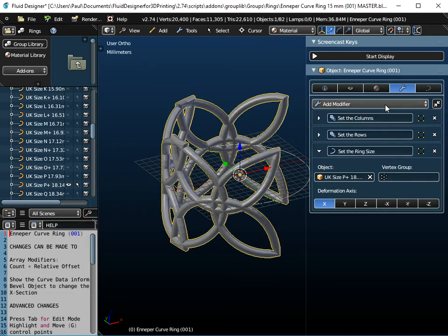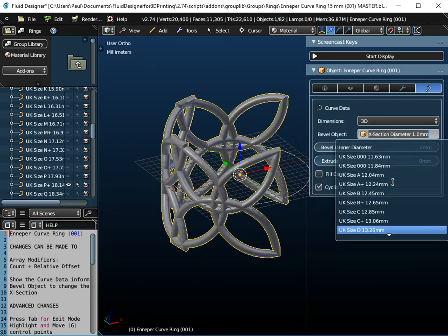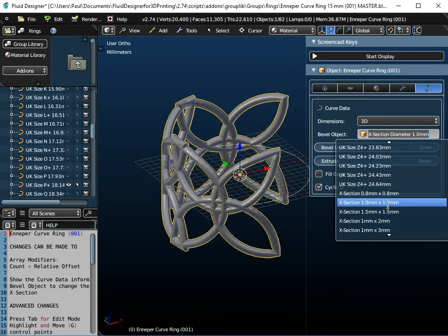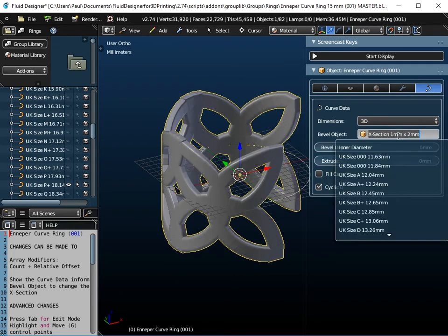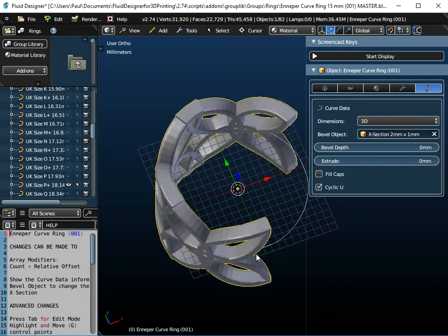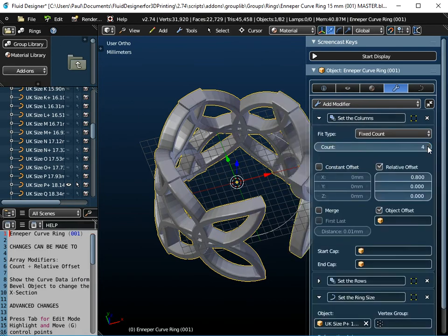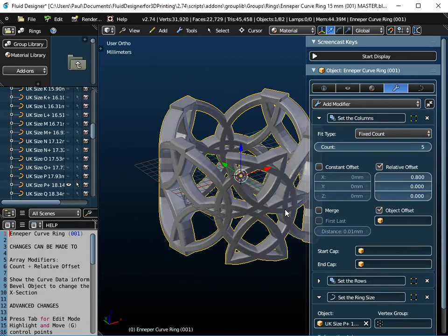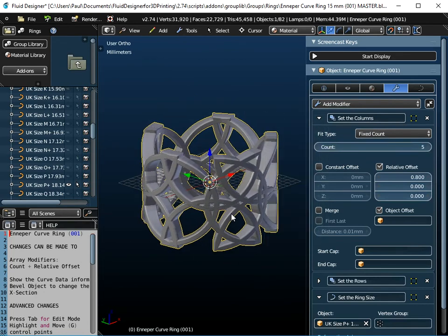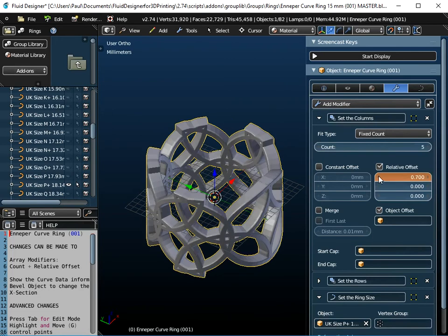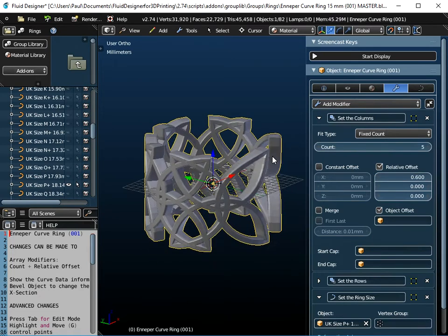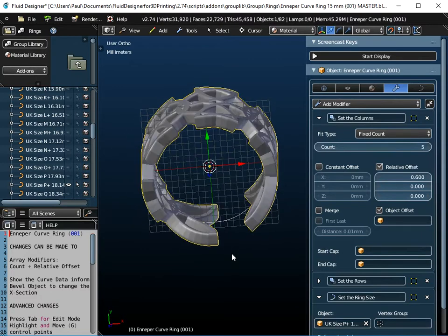But again, because this is a smart object, I can actually change the thickness of it. So I could make it 1 by 2. That doesn't look very good. If that happens, the best thing to do is to just try 2 by 1. It just depends on the orientation of these objects. If I change it to 2 by 1, okay, I can complete the pattern, and again I can adjust the offset values to get different sorts of patterns, so you can leave a gap there if you want or not, just depends on your preference.